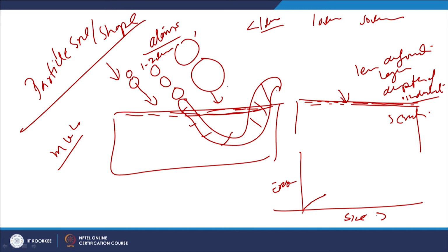Even these particles may get attached to the surface of the workpiece if it is made of very soft and ductile material, which can retain the abrasive particles. Otherwise it may cause plastic flow. Or if the kinetic energy of the impact is too high, apart from the superplastic flow, it may also cause melting of the surface layers.